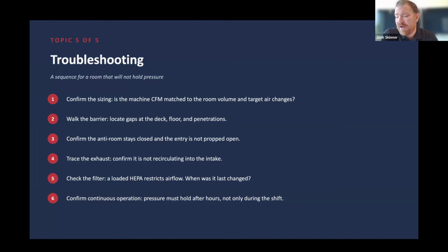Yeah, 100%. So I think there's a couple things. I also want to jump back to something Olivia said in a second too, but we often see machines, especially machines that are venting out internally into other spaces, also use a carbon pre-filter. And if you're doing anything with smells, with chemicals, that activated carbon is the game changer. Like there's no other way to put it. Having that before the HEPA, pulling in those smells and chemicals, which the HEPA is just not going to affect, is super important.